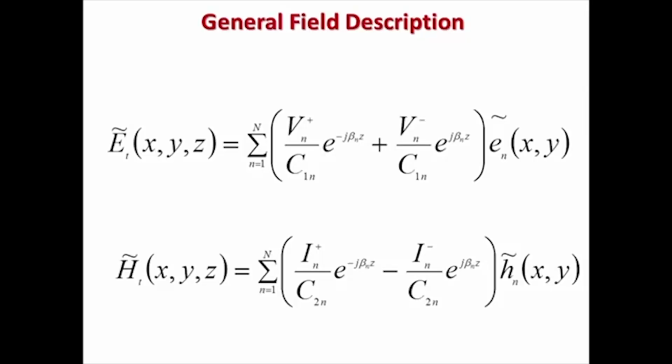You can solve for the values of C 1 and C 2 by enforcing the power equivalence and impedance equivalence. Those are two unknowns, two equations. So, you can find out their values and put those values.